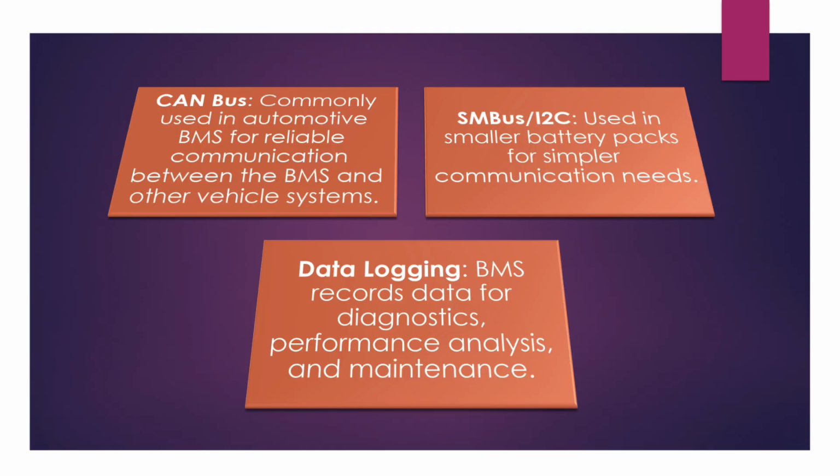Today's topic, communication protocols. CAN bus, commonly used in automotive BMS for reliable communication between the BMS and other vehicle systems. SMBus and I2C, used in smaller battery packs for simpler communication needs.